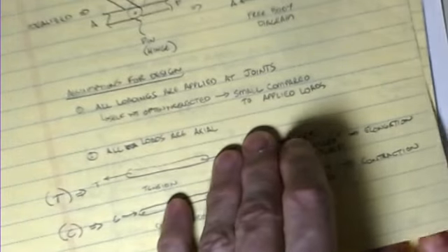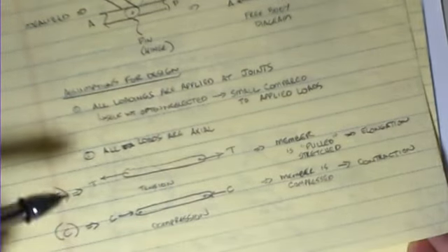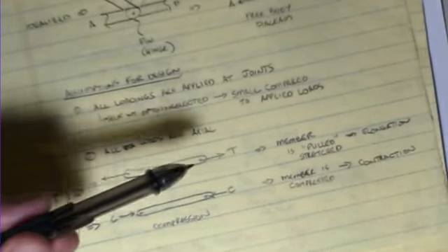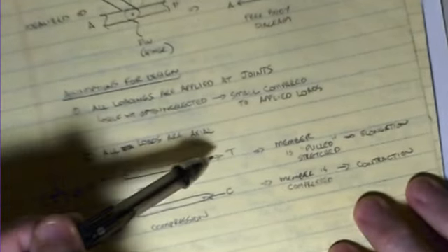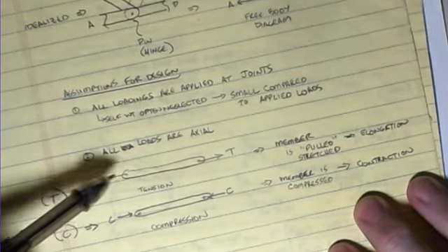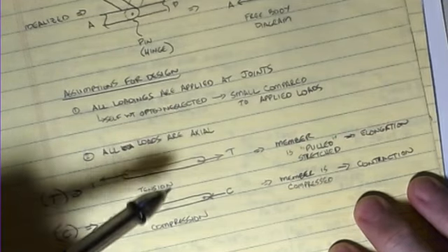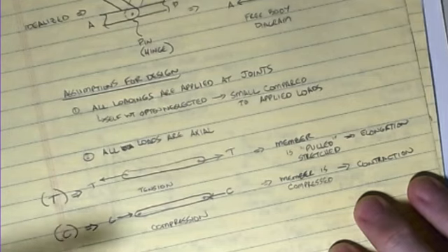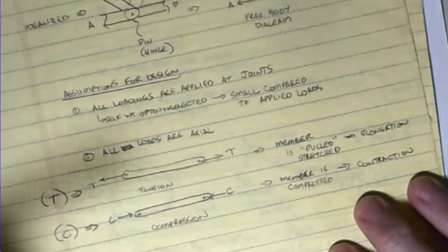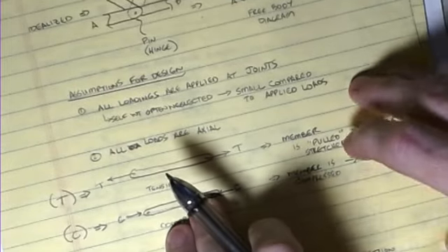All right. This will become important for us as we have to try to define our directions relative to that, because unlike support reactions, I can no longer say that the force is to the right. If you look at this tension member in this first case, here's a force to the right, that is a true statement. But if I look at the other end of the internal forces of this thing, you can see that it's acting to the left. Both of them are required to be tension, so we have to change our nomenclature a little bit. So instead of writing, AY is 5 kips and it has an arrow acting upward, now I have to do something that explicitly tells me all possible cases. So that would be one little change in our thinking and in our approach.